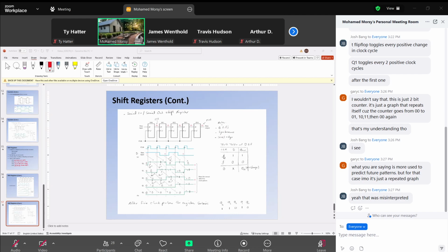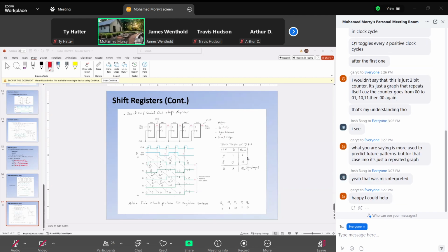Again, the truth table for the D flip-flop is listed here. With the clock pulse, positive edge, if D is 1, we see 1 at the output. We see the data at the output. If it is 1, we see 1. If it is 0, we see 0. But between the edges, where the clock is 0, whatever the input, no change. Qn plus 1 will be the same as before, as Qn. So let us apply here. Put arrows at the positive edges.